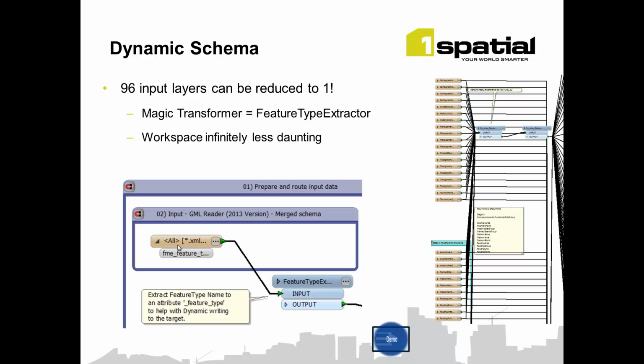It also allows you to take common layers of data, whether that's layers from an Ordnance Survey dataset or layers from your own asset database or your asset layers in multiple shapefiles, for example, pass them all through the same feature type in the workflow, put them through common transformers to carry out common operations on them, like perhaps uppercasing a whole bunch of attributes on all different layers in your data, and then filter those features off in different directions to carry out different operations on certain feature types or feature classes.